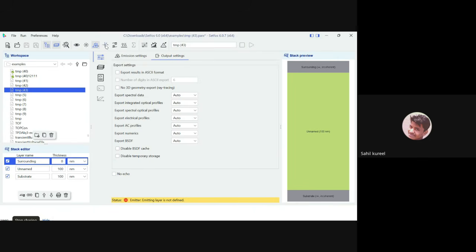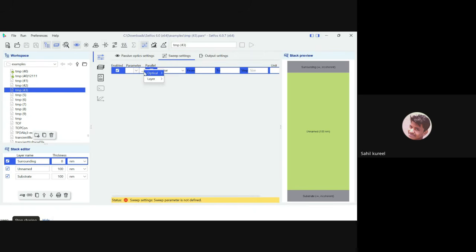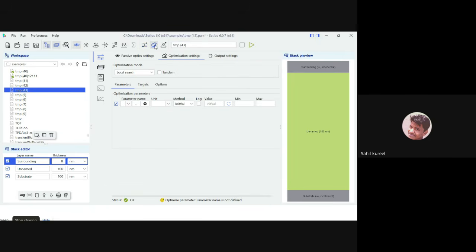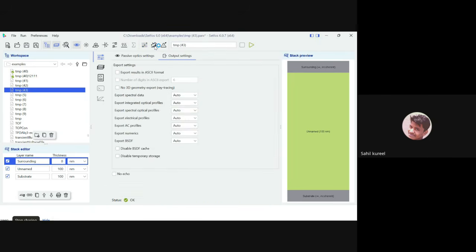When you activate emissions or different features, there is a master equation mode, advanced OLED calculations, Forster distance or different properties for small particles, which you can also do in here, in master equation mode. We have discussed the shift and optimization. It is a shift tab where you can shift different properties. And it is an optimization mode where you can extract your parameters. It is a fit emission zones option, like emission zone fit can also be saved, and you can use it for emission extraction parameters.